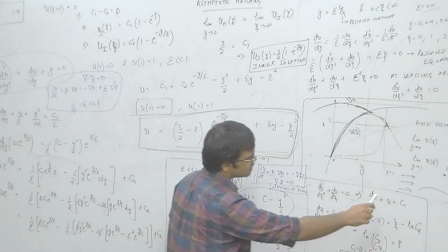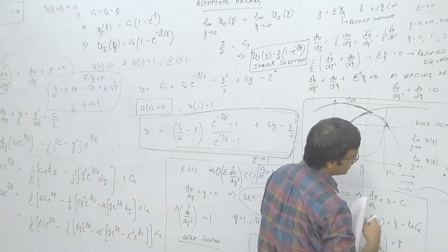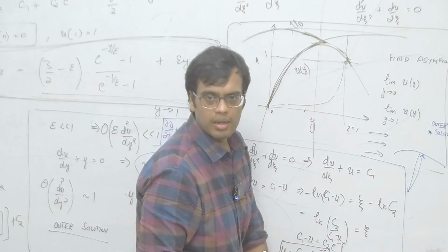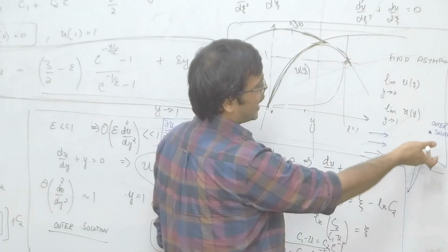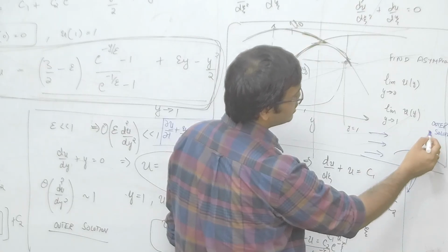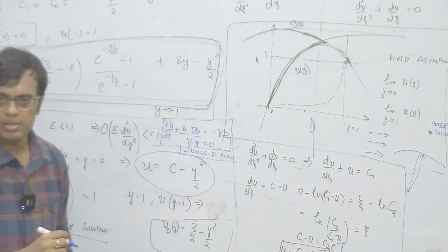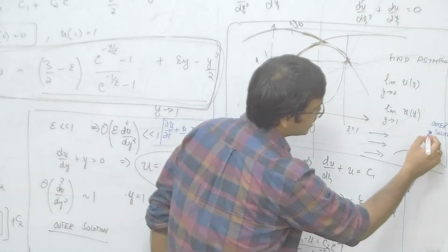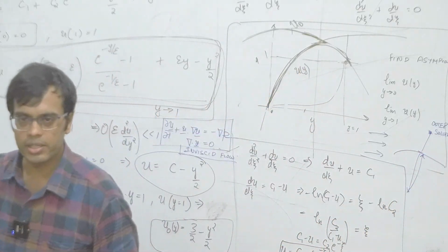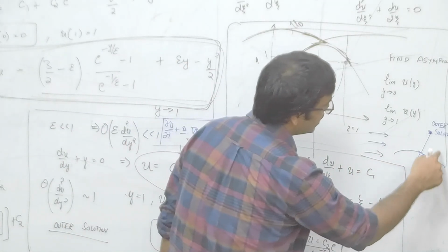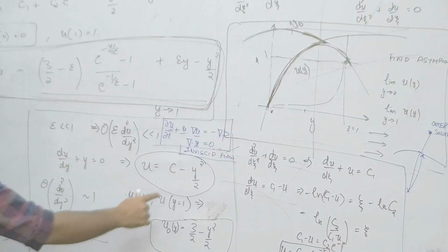For example, in this kind of a surface, if we take the radius of curvature of this surface as the length scale, then any Reynolds number defined using that radius of curvature, if that turns out to be large, then sufficiently far away from the surface, meaning the distance from the surface should be of the order of that radius of curvature, not very small compared to it, your flow obeys inviscid flow equations.